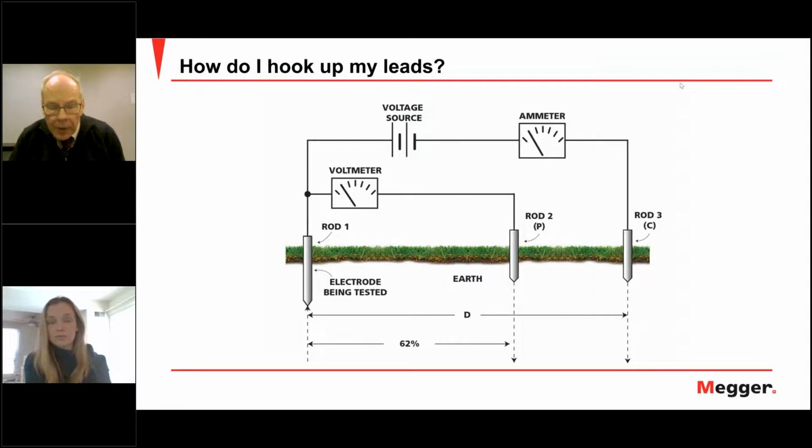The problem with it is, what happens if there's a water pipe or a live electrical line, utility line running underground right there where you put that rod? Well, that's going to influence your reading. So there are a number of pitfalls to doing this. And so the main way of dealing with this is to follow a procedure.